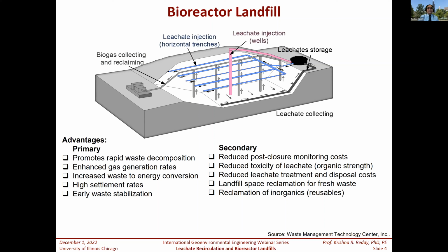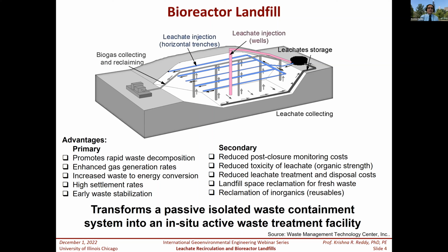I mean, as you see it, why not do this instead of just making a good containment and watching for a long period of time. In fact, if you do this bioreactor landfill operation, you are converting this into a treatment system as well as a containment system. So you have a containment system, as well as an anaerobic biodegradation treatment system happening at the same time. This is very, very good, and a lot of attention is being drawn to this technology.